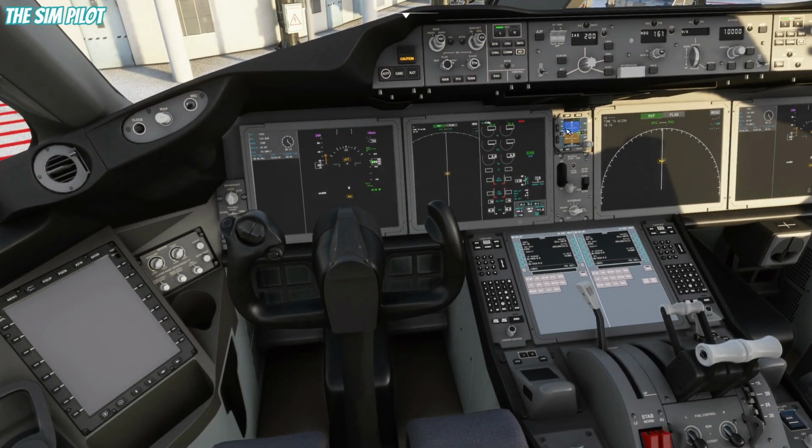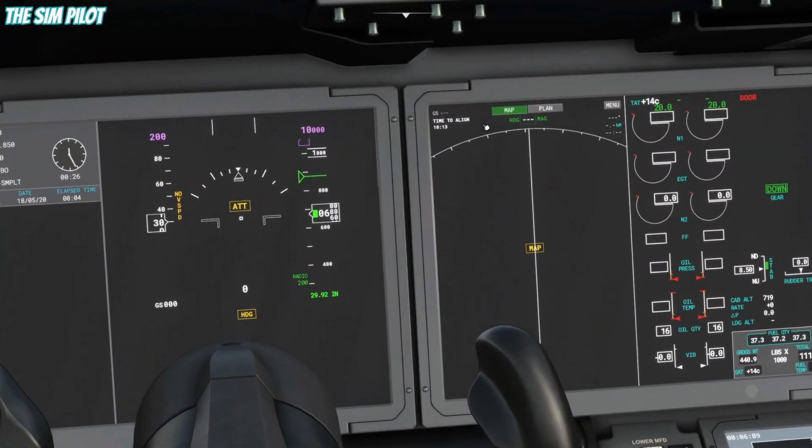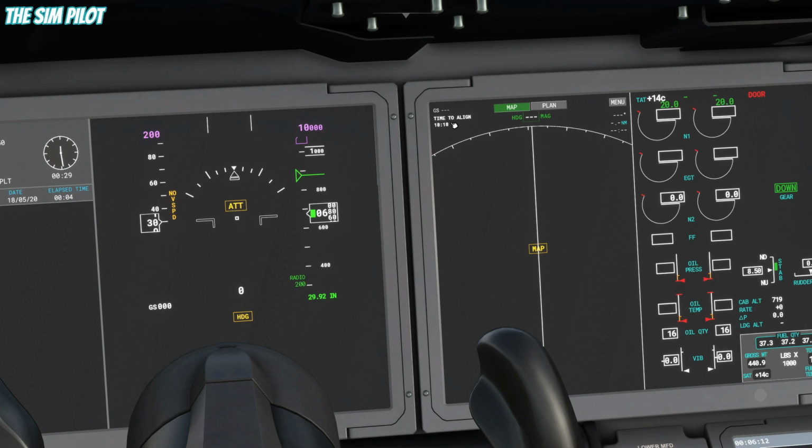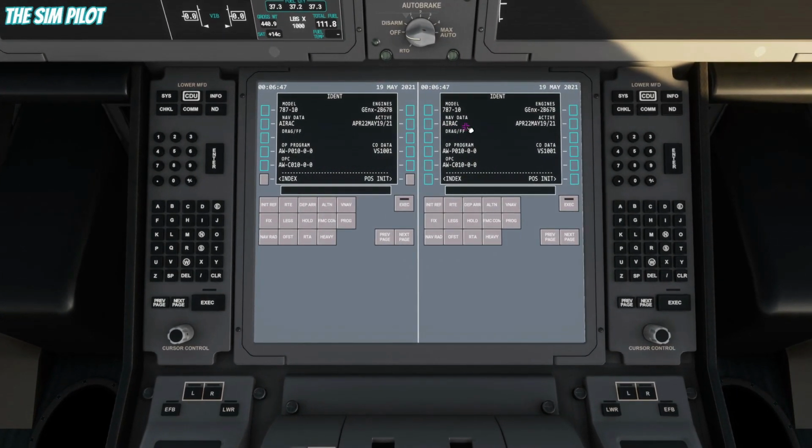And then it starts to align the IRS, and Heavy Division made a different approach to IRS alignment to make it more realistic or close to real life than the Hangar 9 Systems, and it will align based on your location or how far you are from the Equator. And that's how the IRS systems align in the real world. If you are, I think, close to the Equator, it takes less time. If you are far away, it takes more time, so on and so forth. And you can change these alignment options under the configuration menu, which we will look at in a second.